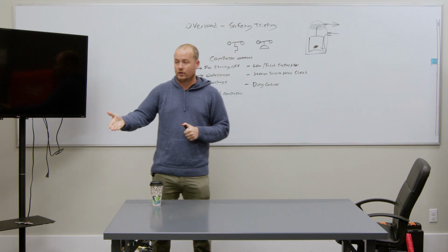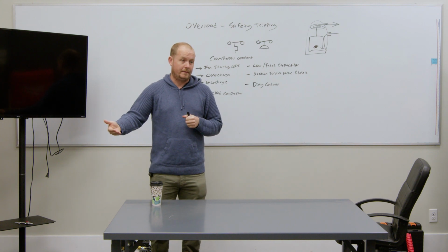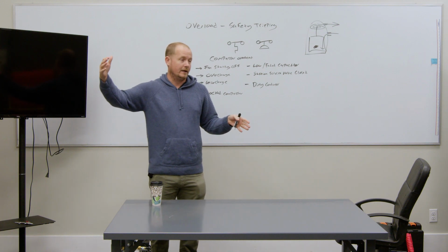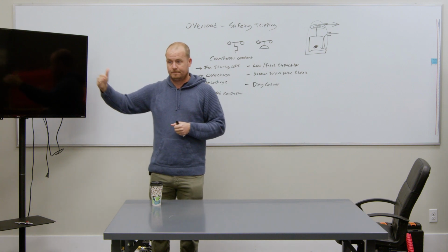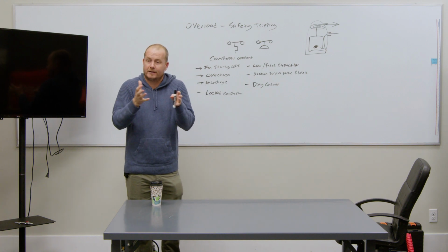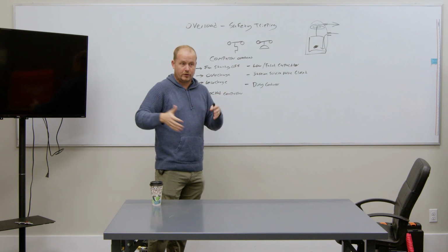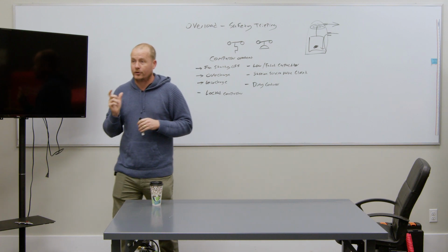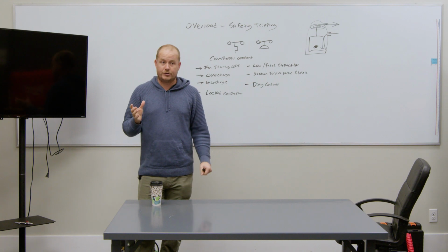So in cases of high current, problems in the compressor can cause the compressor to run hot, but that could be because of mechanical failure in the compressor, or it could be because of a really big compression ratio or a really high head pressure, right? So kind of different things there. How much work the compressor is having to do results in current: less work, less current; more work, more current. But then the cooling side of it is a little bit separate than that, which is why both overcharge and undercharge can cause a compressor to overheat for different reasons, right? Undercharge is because you don't have enough cooling.